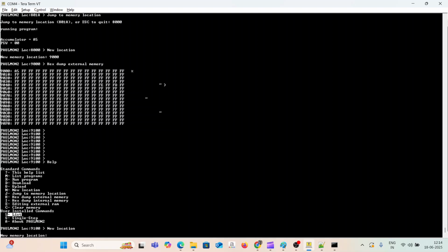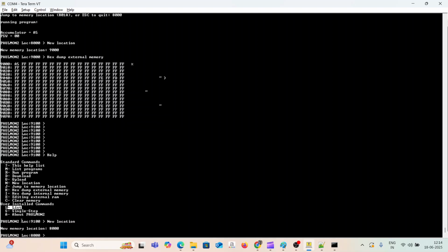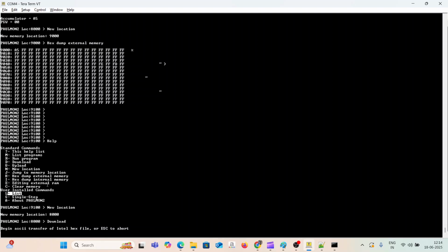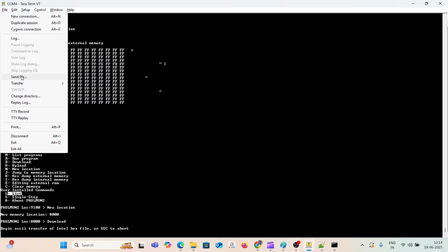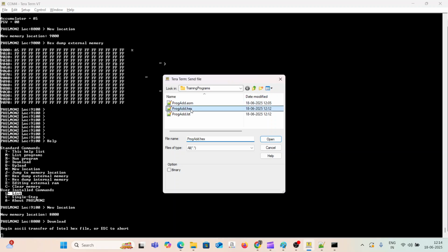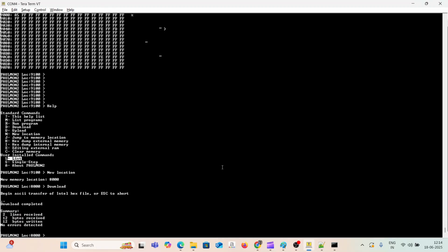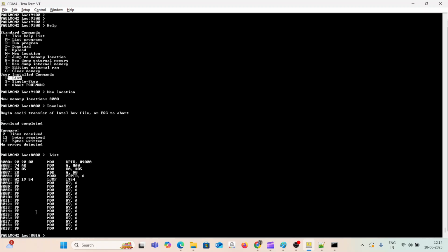You'll see that. Let's go to the 8000 location by typing this new location command. So my prompt is at the 8000 location. Now let me download by pressing the D command. Go here, file, and send the hex file. So it has downloaded the program, no error. Now let's type the list command.